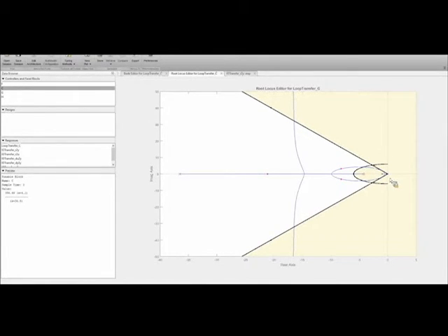But I can move this 0 around as well, and that's going to actively distort the root locus for you. So you can see how as you move a term around, the root locus changes in real time. Which I think is good pedagogically too for teaching, trying to understand how pole and 0 locations affect this, right? It shows you how this is distorting in real time.